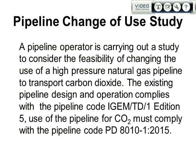Excuse me, from the previous slide, defect assessment. Does it mean something like using inline inspection to check before starting the running of the system? You need to think about that. You need to use the codes and see what the codes would say to you. I think, my view is that most operators, if they were going to do something different with the pipeline, would want a baseline to start that against. Okay, so they want to say, right, well, supposing the pipeline hasn't been inspected for 5 years, would you inspect? And supposing you normally inspect it every 10 years, would you inspect it before you start operating? Well, that's a reasonable position, so you need to build that in.